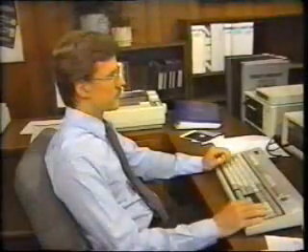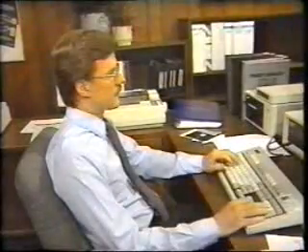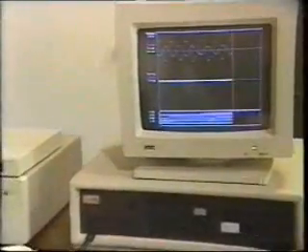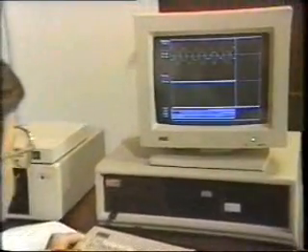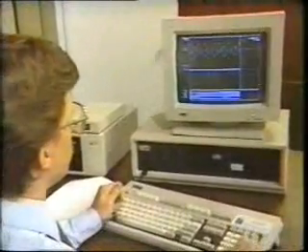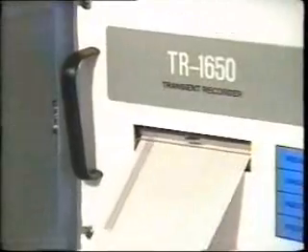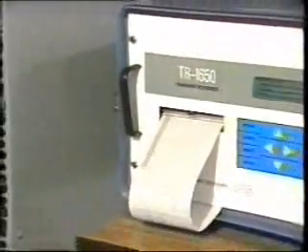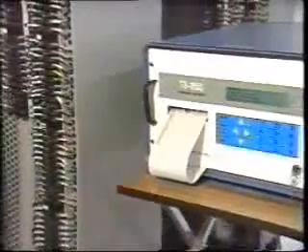A distinctive advantage is the capability for immediate remote retrieval. Information from various locations can be brought into a master computer for analysis at a central location. In this context, another advantage is in the precise timekeeping of the digital system. Yet another advantage is the capability to adjust the individual trigger set points from remote central control. In some digital systems, a printout of equipment status can be produced similar to the SER.